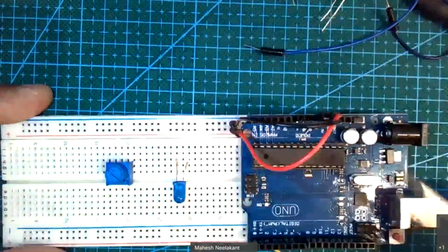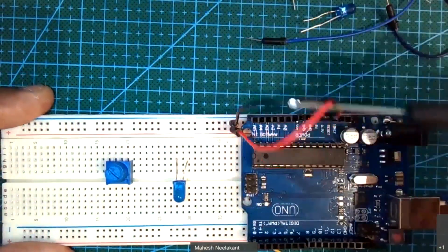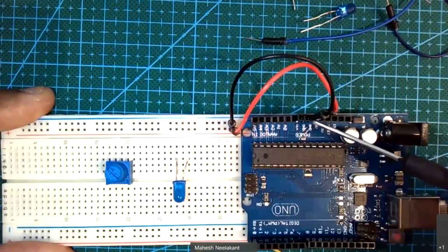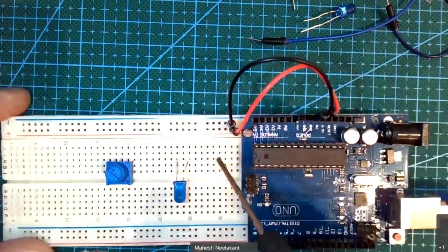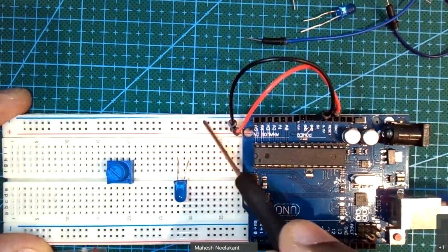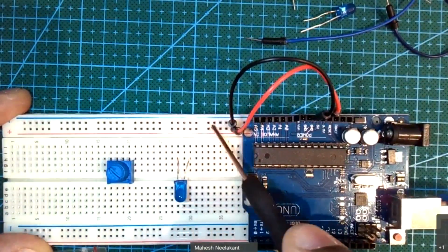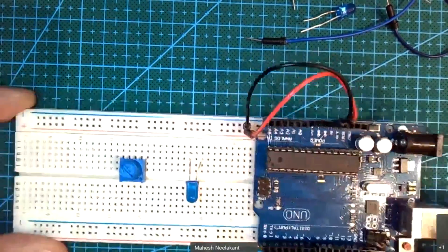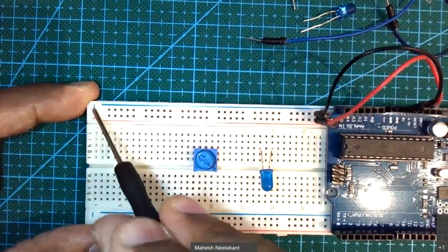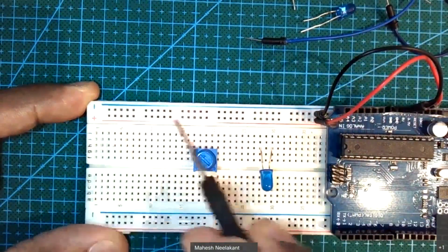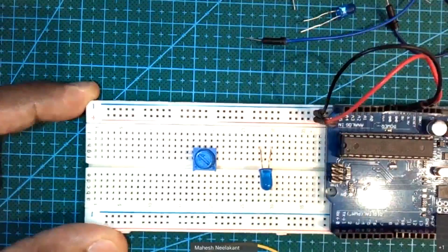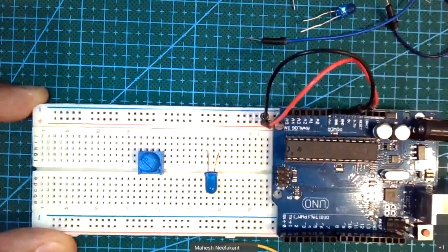Okay, so remember, what this does is it can generate 5 volts of electricity, just like a battery. And this is the negative part of it, or ground. And when you connect it here, that power is available across all of these pins, these holes in here. So that's why you see this little positive. One second, let me move this over a bit. That's why you see this little positive and negative over there. So normally you connect up. So this is kind of what's called a power bus. You can get your electricity to your devices from this. Just going to move it back over here so we can focus on the parts we're interested in.